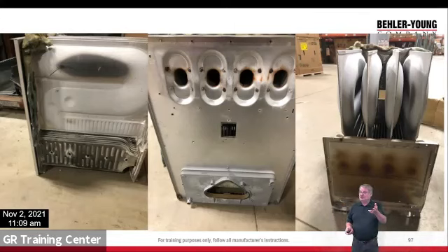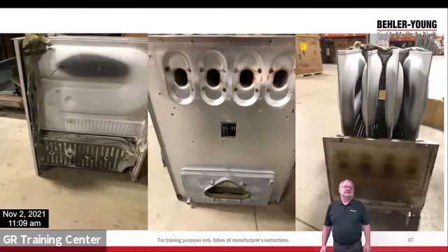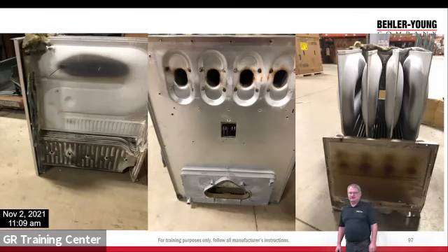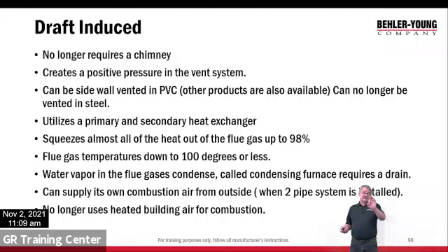Now, 90% or plus, we got a 97, 98% furnace now, to where 98% of the heat is coming into the house. Okay. Now you can see that heat exchanger over there on the far left has actually got a crack in it at the top there. Okay. Now, crack, obviously we can leak flue gases into the house. More likely we're going to suck house air into the heat exchanger because the heat exchangers are generally under negative pressure. So again, that center is where my draft inducer is on a 90%er.